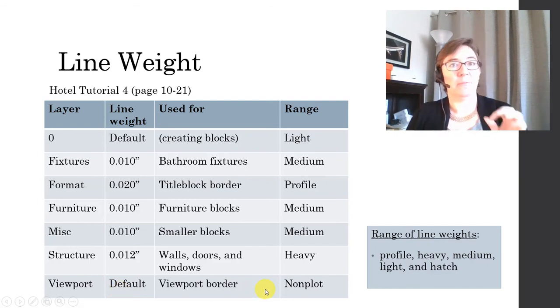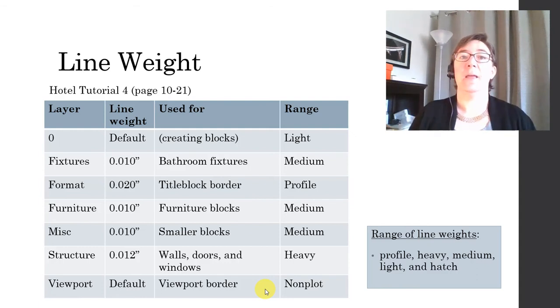But the whole point of putting your viewport on a separate layer is that you can turn it off, and so it won't print. And I call those layers that you intend to turn off non-plot layers.